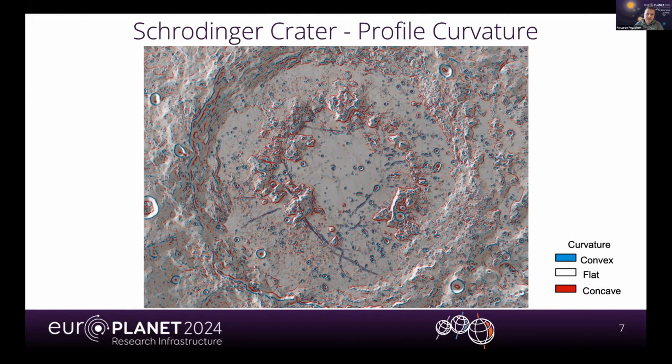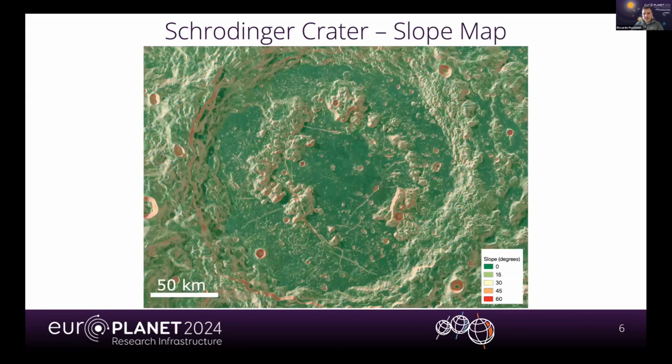And you see that here you start to see other things. For example, before, if we go back, we see that, of course, the Pickering area is very steep. We have steep slopes, I think around 45 degrees or even more here. Here is around 30 degrees, which is a lot. You have to imagine that normally Mars rovers can climb up until 15 degrees of slope maximum, but the safe threshold should be around 10 degrees of slope. So these are completely outside our range of tolerance.